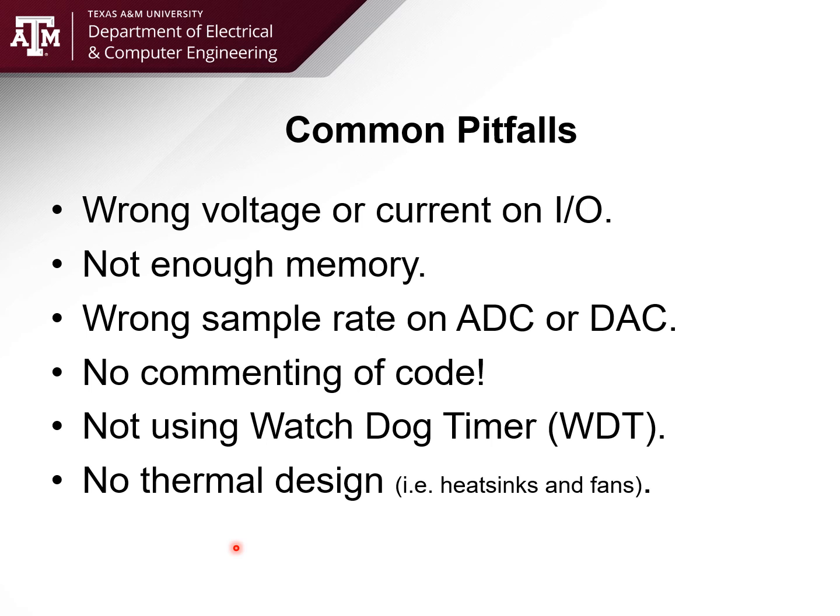There's a reason for that, because heatsinks do cost a little more money. You're going to want to purchase the heatsink with it, because as soon as you start using the microcontroller, actually not just sitting there idle, but actually computing, it starts to heat up. This is especially true of senior design, about mid to late semester in 403, the senior design course, I will get a request to buy another Raspberry Pi because the Raspberry Pi died. Why did it die? It overheated.